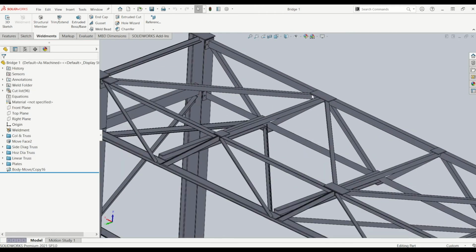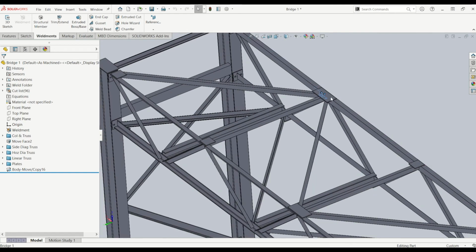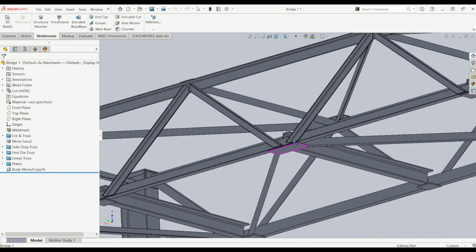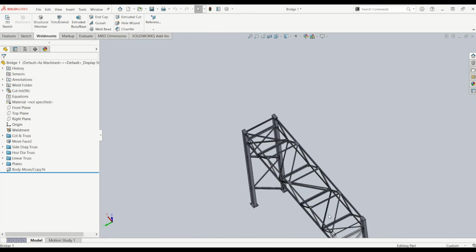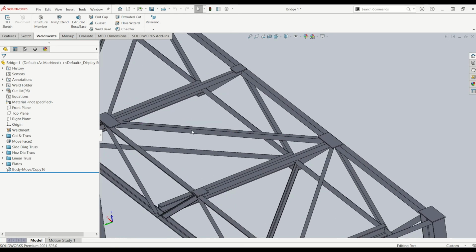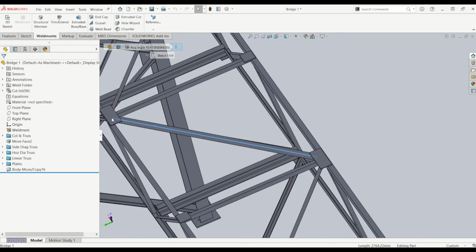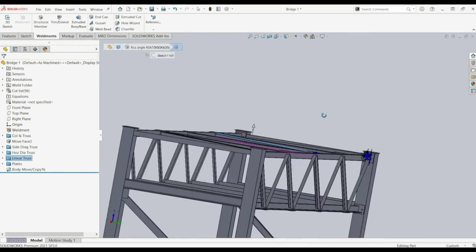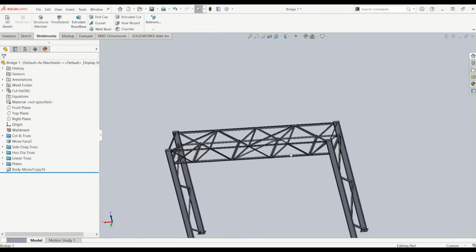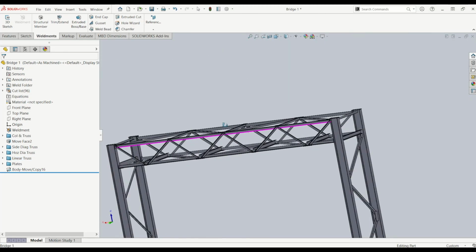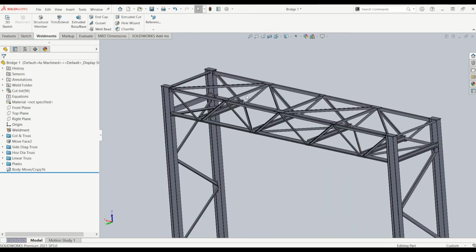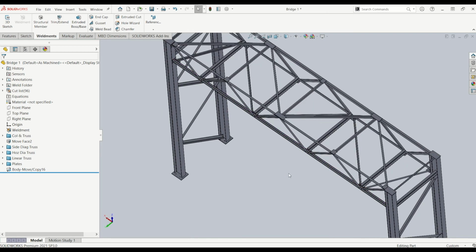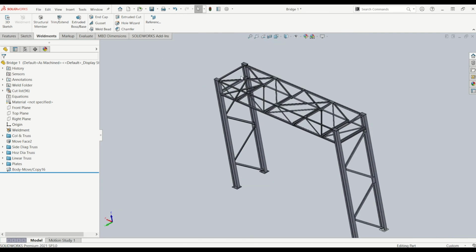So now if you follow the same principle, creating the base plate on a sketch for the top plane and the base plate on the sketch for the bottom plane and pattern it, you can actually very easily put the cross members in. And also I've put some extra reinforcement by just doing the same principle from the center of the plate, doing a diagonal line and putting in a strut as well across the top, just for a bit of reinforcement, and I've done the same on the bottom. I know that was a quick video, but there's no point in you watching me just pattern everything. But that's the principle you need to create the top.